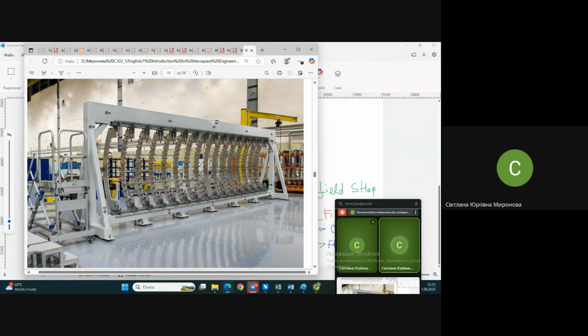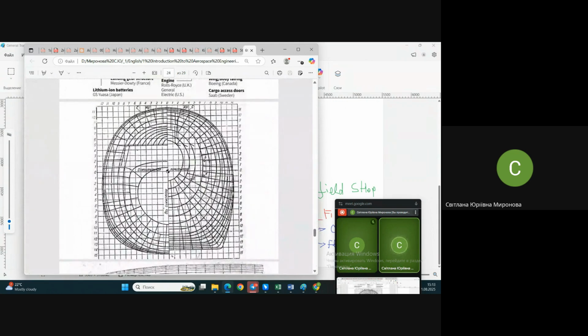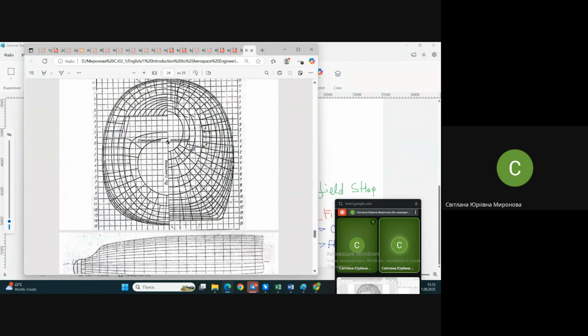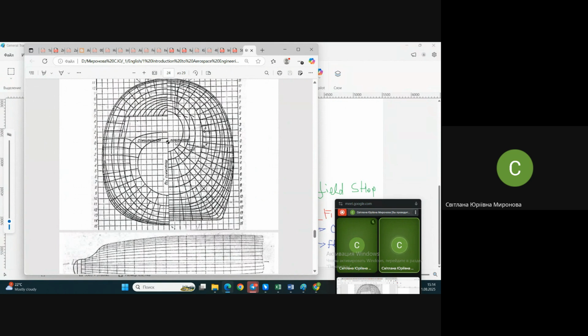Actually, we in aviation, in aircraft manufacturing, have stolen something. Do not tell anyone. But actually, any aircraft engineer knows this. Such a beautiful picture is called a loft. In English, loft has the same meaning as attic, the top floor of any building, covered only with the roof. Something like a technical floor, which has only a floor and a roof. That's it. When the aviation age started and we needed to produce dozens of airplanes already, we copied and developed, of course, the technique that had been used in ship manufacturing, in sea transporting vehicles.